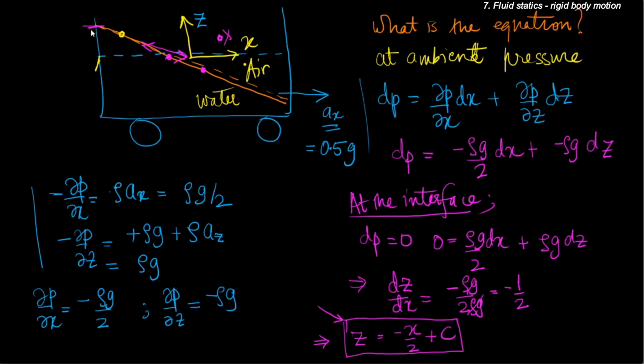And the way to find the intercept is that given this shape exists, given the dimensions of the vehicle, I can find out the volume of water in the deformed condition in terms of the offset, and I know how much volume already existed in the vehicle or in the tank mounted on the vehicle in the initial time. Because there is no water sloshing out as such, we can equate these two volumes and evaluate the value of the constant. It is as simple as that.